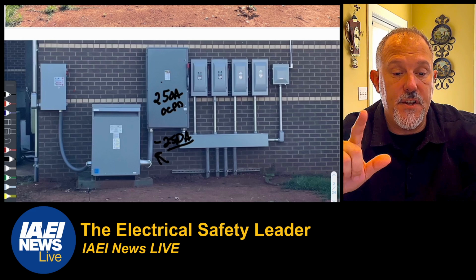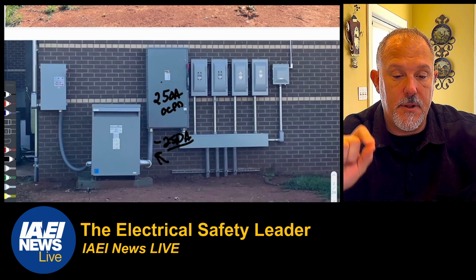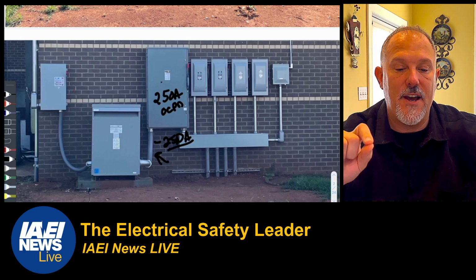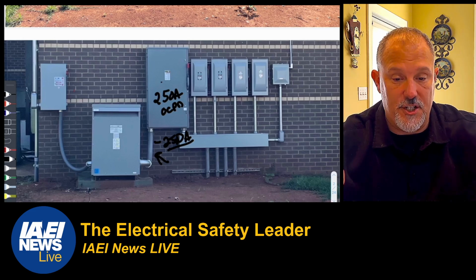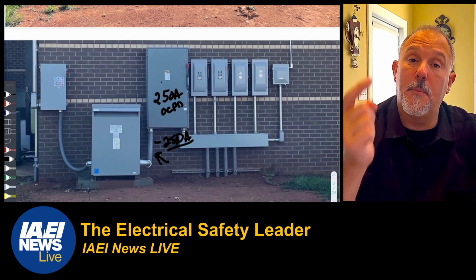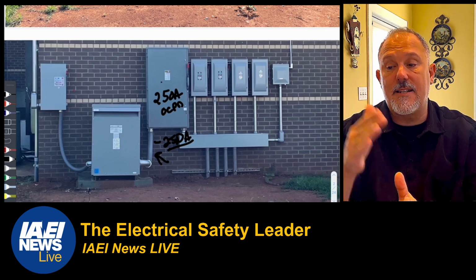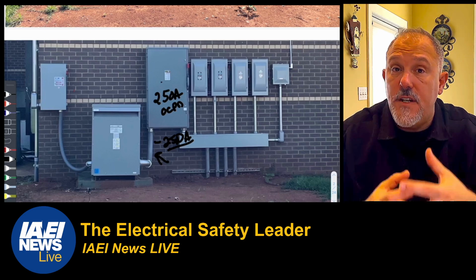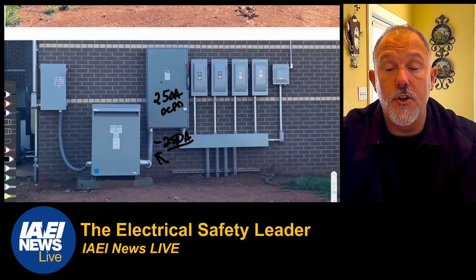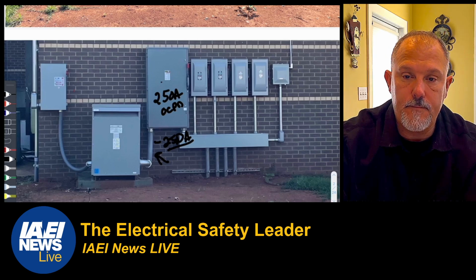And then finally, for field installations where the secondary conductors leave the enclosure or vault in which the supply connection is made, the secondary conductors shall have an ampacity that is not less than the value of the primary to secondary voltage ratio multiplied by 1/10 of the rating of the overcurrent device protecting the primary of the transformer. So again, if it extends beyond, if you're not providing all that physical protection, then they want that overcurrent protective device on the primary to be of no more than a certain size as a ratio for that secondary conductor.